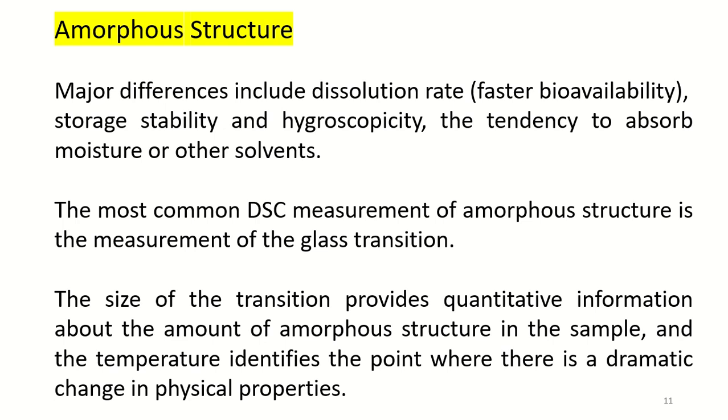Below the glass transition temperature, there is limited molecular mobility, while above there is high mobility that would result in much lower viscosity and potentially much greater chemical interaction between components. So this is the reason to store these types of materials at least 40 degrees Celsius below their glass transition temperature.